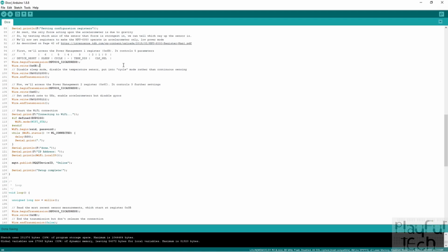Because I mentioned earlier about battery and power requirements, it's a good idea to reduce the number of functions that are running that we aren't really making use of. So what we're going to do is turn off the functions on the board that we're not using in this project, only leaving on the accelerometer readings. The other thing we're going to do is reduce the resolution of those readings, because we don't need to be updating them 1,000 times a second for this project. We can do it much slower, and that again is going to use less power.